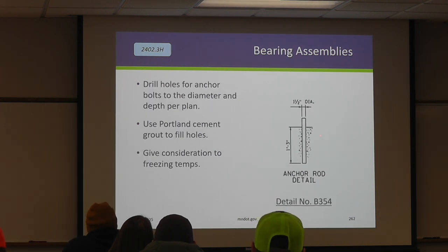This is our typical detail. So we're going to embed an 18-inch rod in. We have just a little bit of stick up. This number is detailed on the plans. It does vary a little bit, which is why it's not shown here. But you're going to core this in and then you'll put grout to fill that hole.